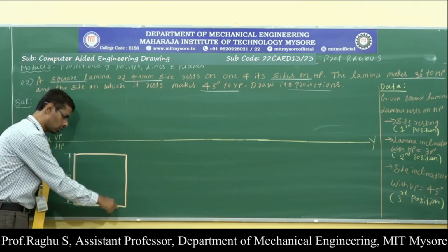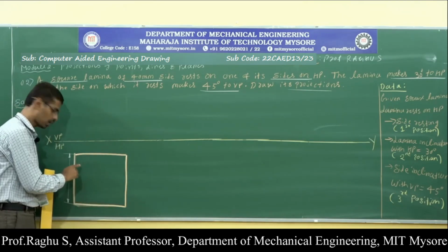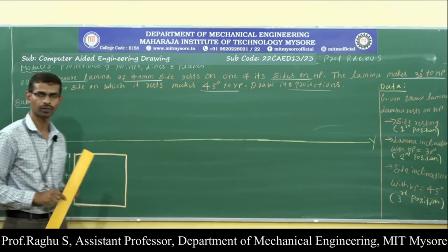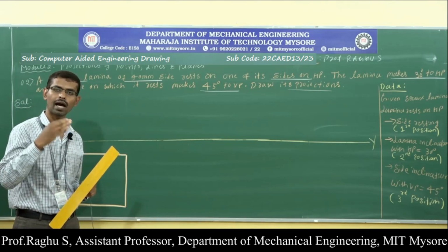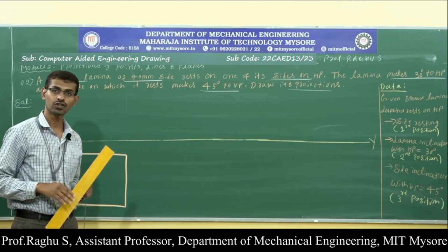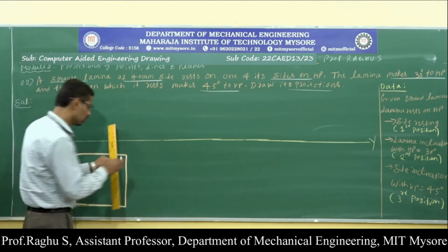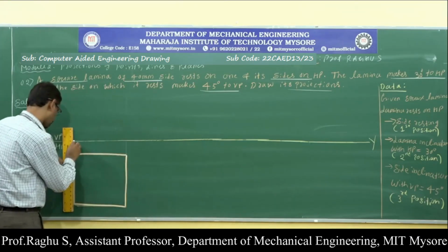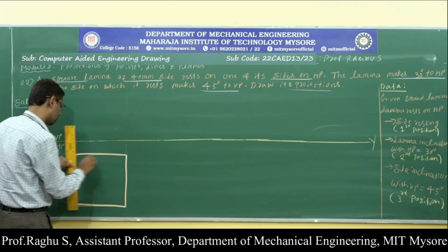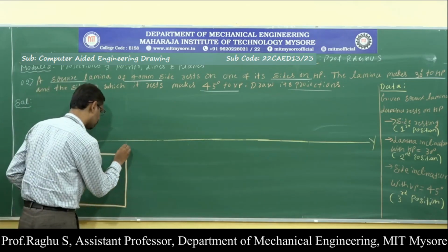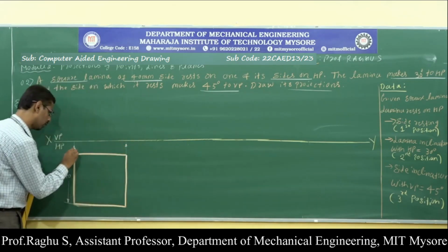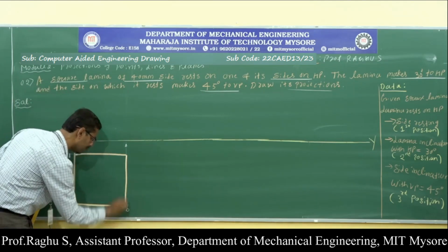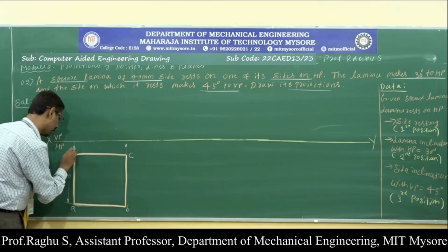So this is the true shape, square lamina, extension line and dimension line. I have completed the top view. Next, in the front view, the lamina looks like a straight line. To get the front view, just draw thin lines, draw upward projections. Draw upward projection means draw thin lines up to XY. Up to XY. Before that, do the naming. Corner A, B, C and D.